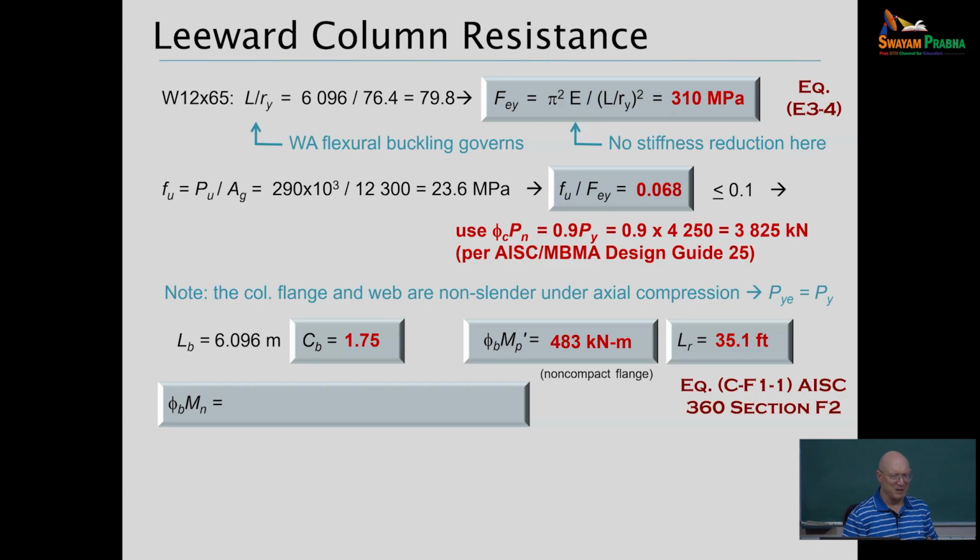In practice, we have a very convenient rule that works pretty well for rolled sections. It works very poorly once you get into some other types of sections, so I'll show you some things about that later. And that's what we do: we just scale the uniform bending moment diagram by this moment gradient modifier, and if we're lucky, in which case here, that's 1.75.